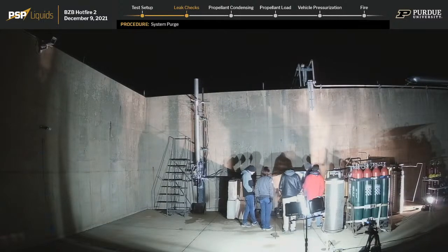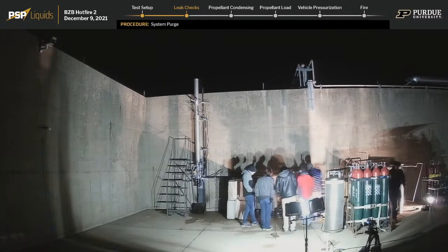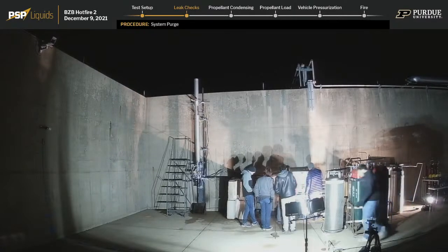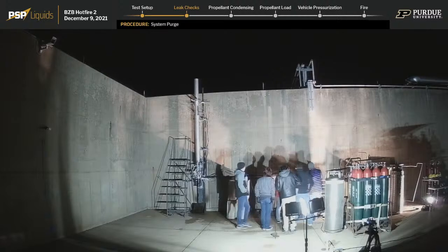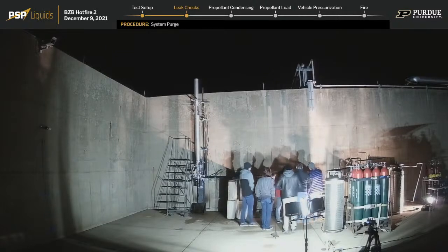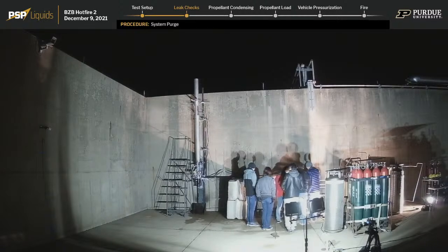Yeah, so essentially we have TVFU05 closed. We have an outer jacketed tank to our condenser, and then an inner tank that our methane actually goes inside. And we have a coil of tube going around the inside tank. And by flowing liquid nitrogen through that tube, it causes heat transfer into the wall and can chill the entire condenser. Close MVN202. MVN202 is closed.